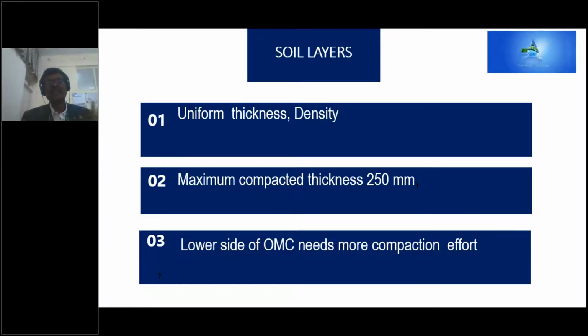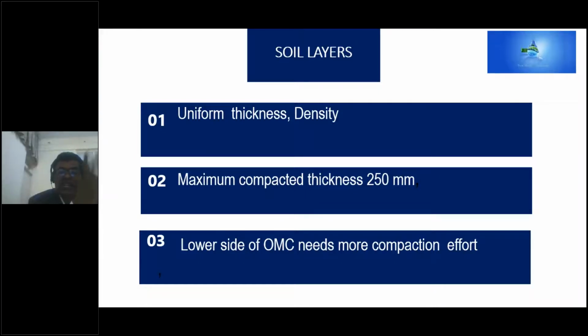Everything it tries, it stabilizes, but that takes time, 3 years, 4 years, etc. So what we are doing is compaction, not consolidation. So we should not make any mistakes, especially in the foundation layers. With any mistakes, the financial implications are more. I am not saying we can make mistakes in the top layers, but the financial implications and the risk involved are more here.